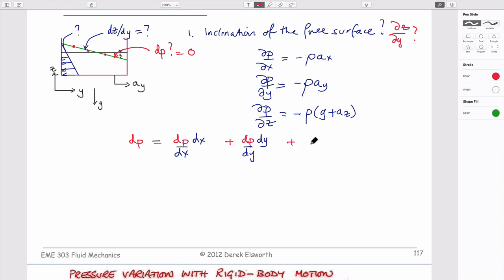And we can finally add a pressure, dP, which again we multiply by 1. So these are just ones, so that's fine. But you could argue, I suppose, that the change in pressure is equal to 3 times dP. But they're not, right? Because they're all orthogonal. So as you move in one orthogonal direction, the other ones are independent of that. That's the one kind of condition of orthogonality, if you like. That's why we resolve in x and y directions, because the forces in the x direction have no impact on the forces in the y direction.